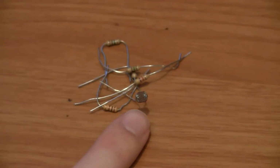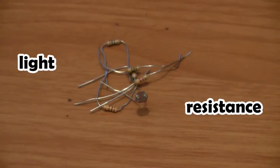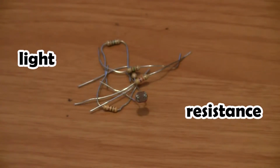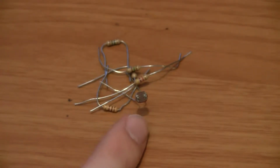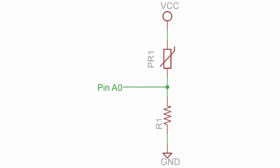For our first sensor, let's use a simple photoresistor. Photoresistors simply decrease their resistance as the ambient light in the room increases. As I decrease light in the room, the resistance will increase. So if we hook this up in a voltage divider circuit with a fixed resistor, we can essentially feed into the Arduino a voltage that varies with light in the room. So let's hook that up using this schematic.